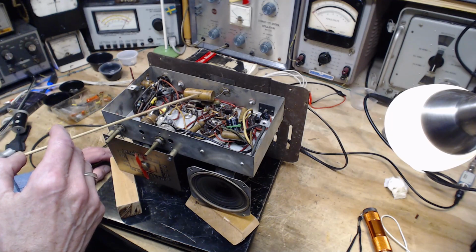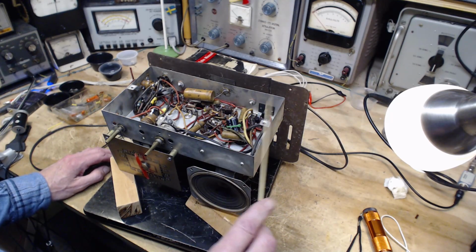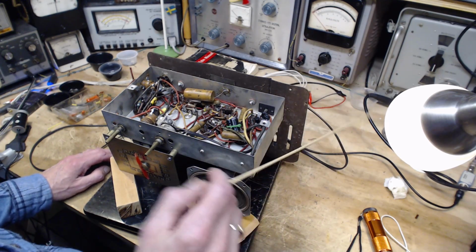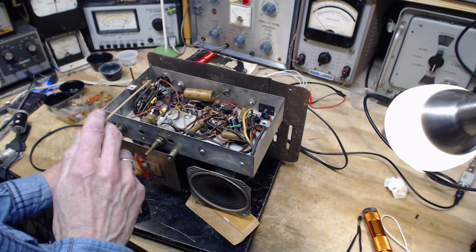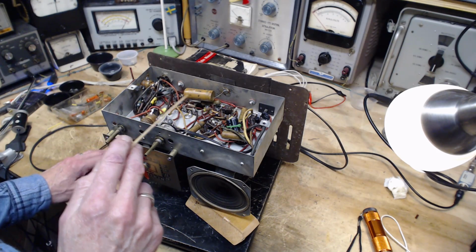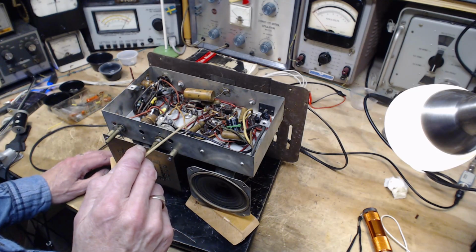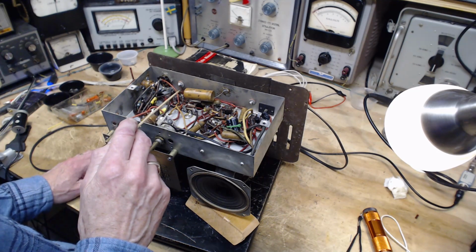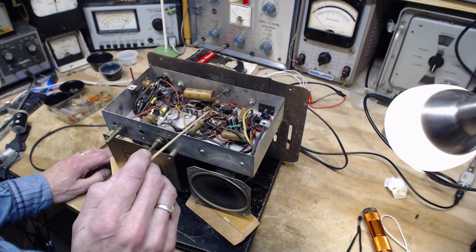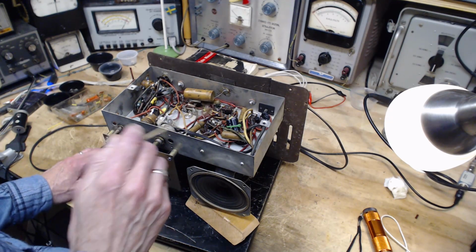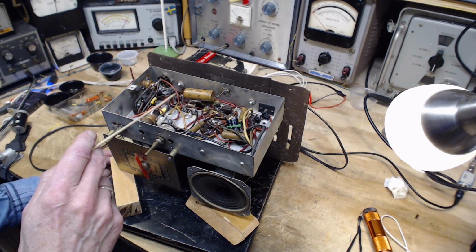You throw a capacitor in, a couple capacitors in, you can change that from a pulsing RF rectified voltage to a nice smooth DC voltage. And you can use that negative voltage to operate the grids, and isn't it handy when that negative voltage goes up because the output of the IF has gone up, then the negative bias increases and the tube's gain is reduced. So it's just a happy coincidence that all this can be done in such a simple way and so handily in these radios. And that's why all these radios utilize this automatic volume control.